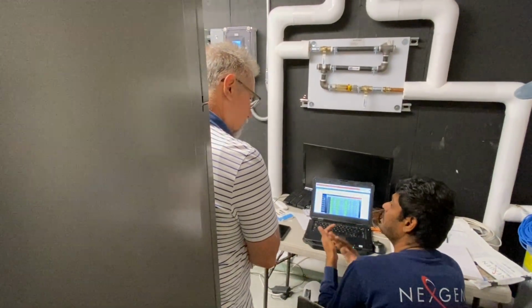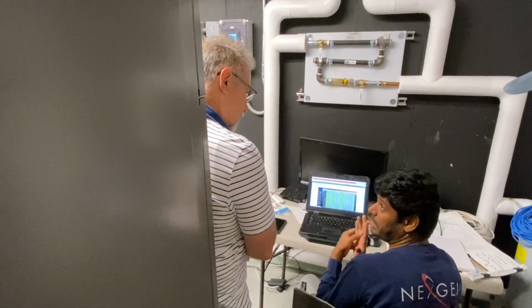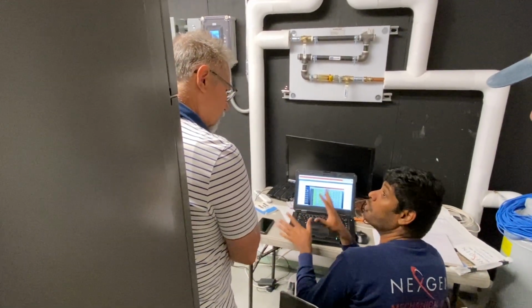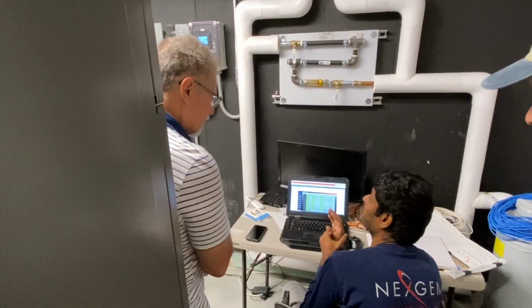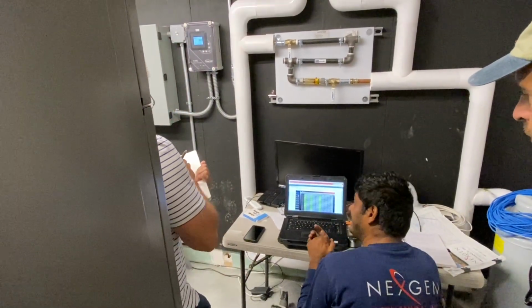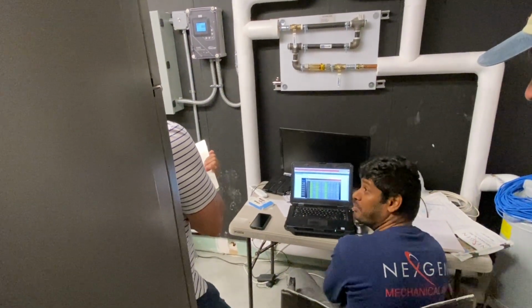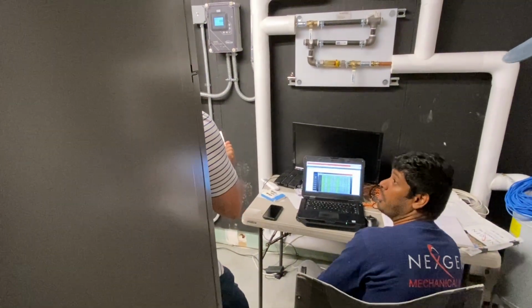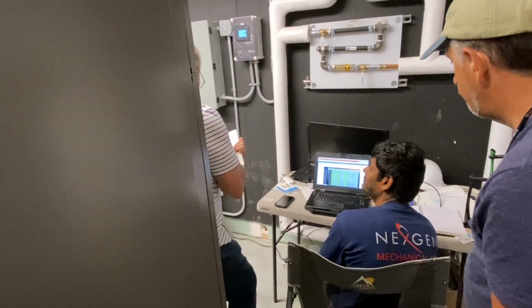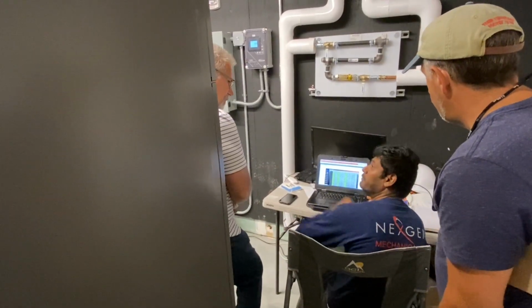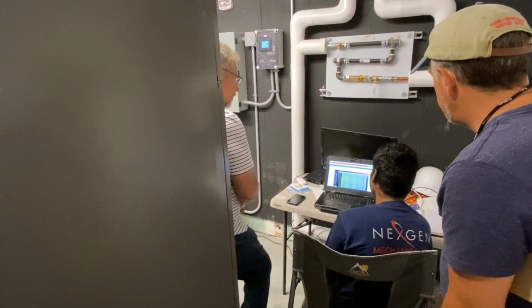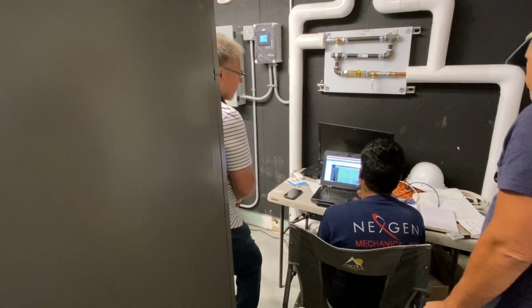And the valves are not maintaining any discharge air temperature at the VAV, they are maintaining only the space temperature, right? And most of the toilets and the hallways are two position, they are not modulating. Probably they are less than 1 GPM, and they're going to go on and off based on the space temperature. So basically that's what we have.